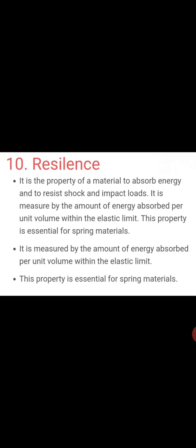Next, resilience. It is a property of a metal to absorb energy and to resist shock and impact loads. It is a measure of the amount of energy absorbed per unit volume within the elastic limit. This property is essential for spring materials. So it is how much load a spring can take. That amount, that measure, is nothing but resilience.